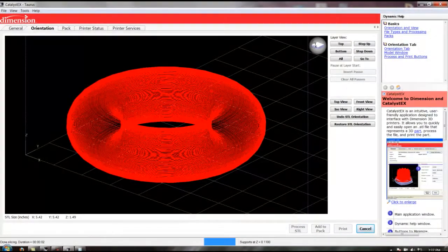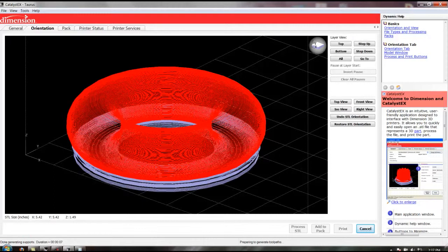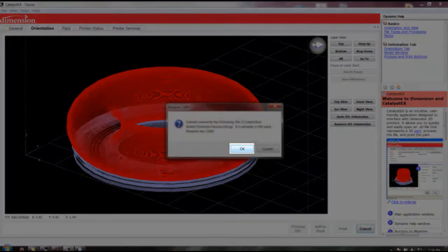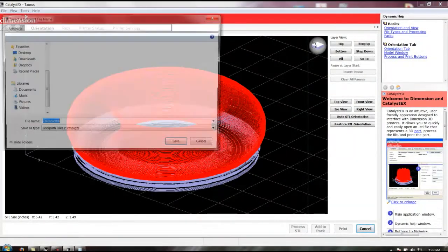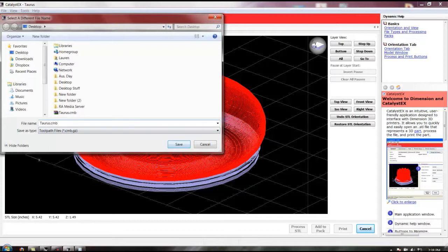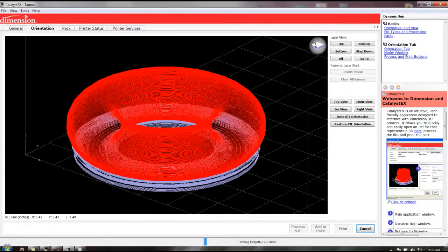Another way of making this particular model cheaper is by giving it a hollow section through the solid area. Now, if you're dealing with walls or rods with your 3D print, you need to make sure that they've got an appropriate thickness, or otherwise they'll be too thin, and that appropriate thickness is more than 2 mil.